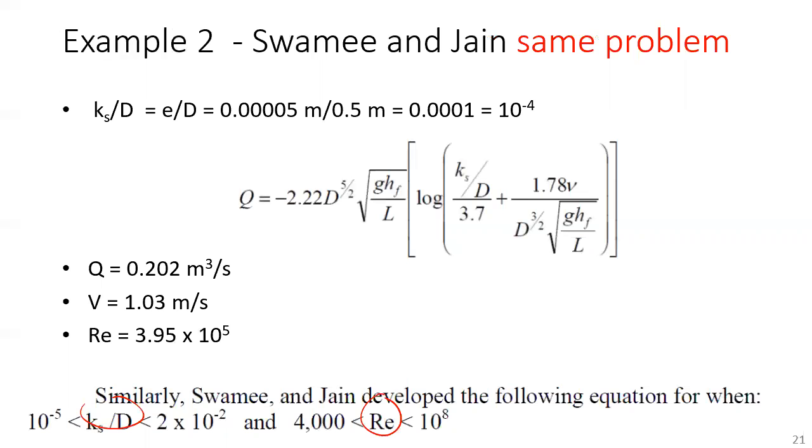So the Reynolds number is about 4 times 10 to the 5th. That's certainly within range. And the relative roughness is 10 to the -4, which is also in range. So basically you meet all of the qualifying criteria to use this equation. So the answers from part 1, where we used Re f to the 1/2, and part 2 are both acceptable. That answer in the middle, the second method we tried, isn't.